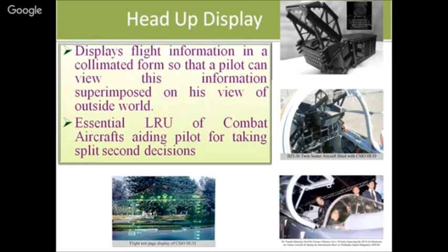So the basic philosophy is that the head-up display symbology should not disturb your ambient view, or it should not cause any tunneling, where you get immersed in it and forget the outside world. So with that ideology, we develop the HUD in a manner that the image is focused at infinity, thereby ensuring that the pilot is able to see the ambient as well as, with ease, the superimposed imagery.